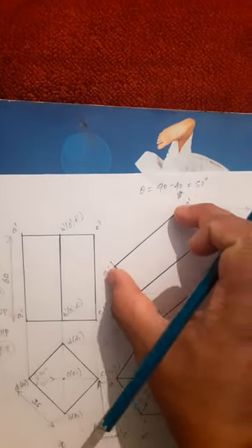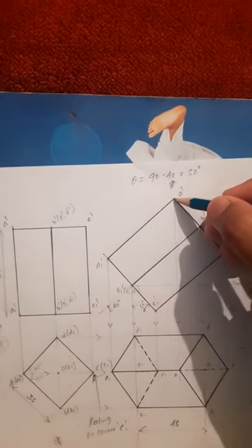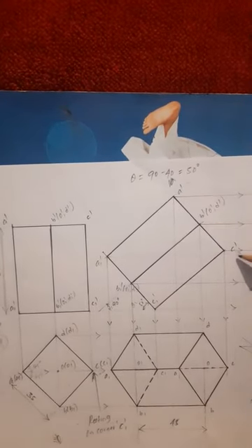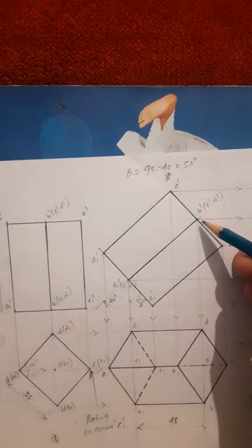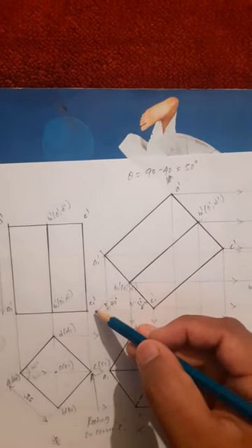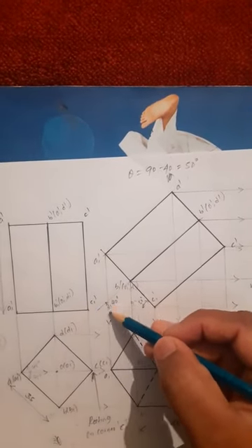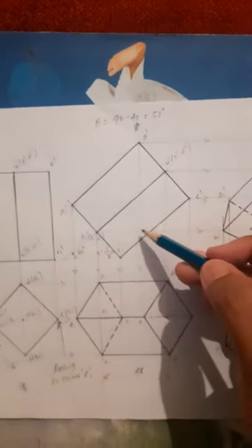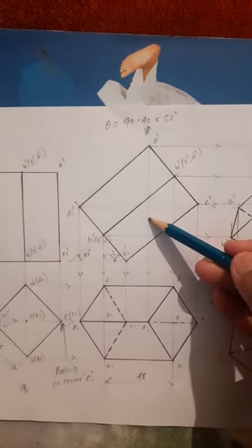Axis length is almost 60 mm. Now mark the 60 mm and join all those corners. There's A dash, B dash and C dash. Now extend this edge or the axis. It touches on the XY line. You measure that angle, how much do you get? 40 degree, right? That is the second position, front view over.